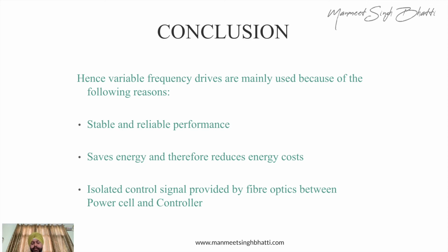The next benefit is that an isolated control signal can be given. For all the VFDs which need to be controlled, you can nowadays use fiber optics. So you can keep your controllers anywhere in your plant, with power control in a different MCC, and you can still control it. These are the kinds of technologies available nowadays with the VFD, and as per your need, you can design the complete system, and it is going to get you the savings.